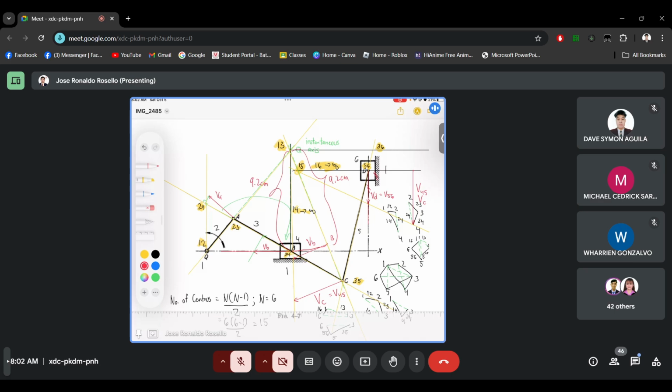Then based on the centro polygon, I determined the locations of the centros because we will have to find the right centro as a reference point to determine velocity D. So now I have determined velocity D. Okay, for the conclusion of this example, we'll just have to measure the velocity D, the vectors of velocities, then multiply it with the velocity scale, kV.